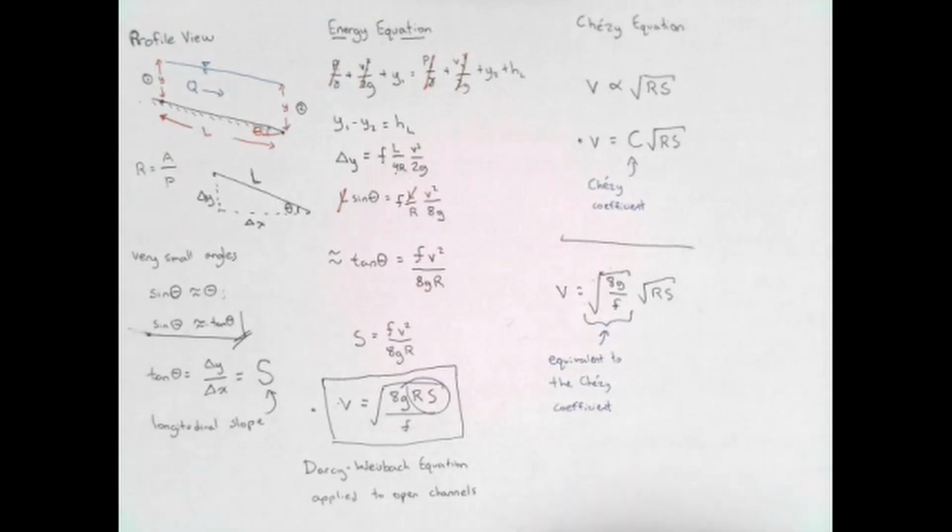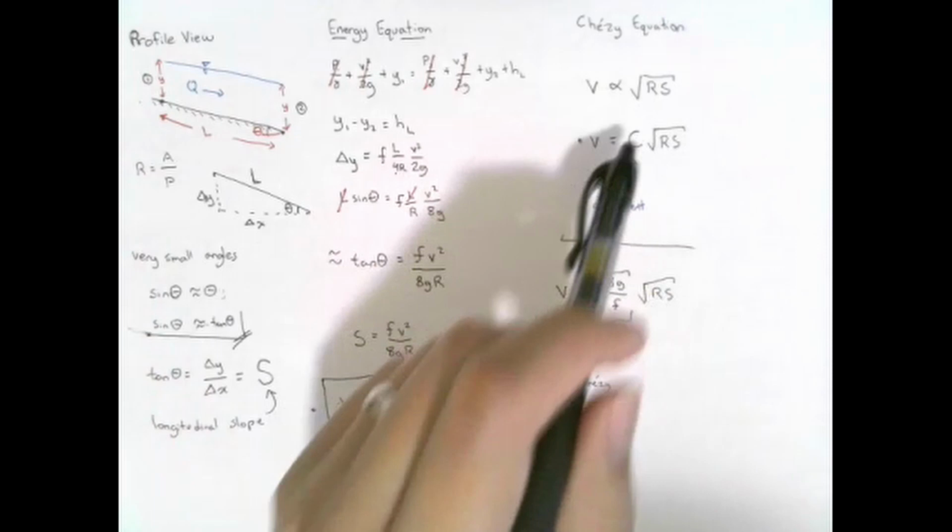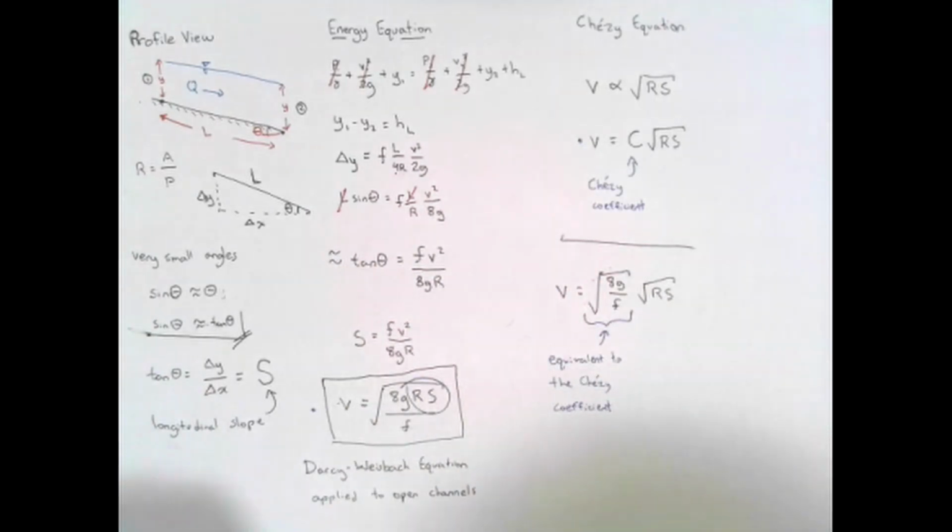Now, the Chezy equation is actually very rarely used nowadays. Typically, we water resources engineers use it when we want to have a very, very rough estimate of flow rates. But if we're calculating some very specific, very exact values, we wouldn't really turn to the Chezy equation. Because several years after Chezy derived this equation, an Irish engineer named Robert Manning came up with another equation that we call Manning's Equation that calculates velocity and takes into account the channel's geometry in addition to the roughness in order to calculate this coefficient.